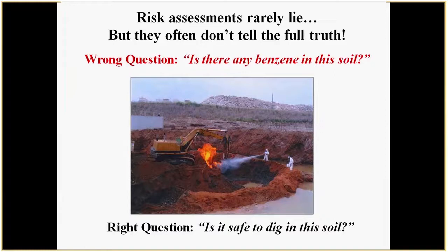So the right question is, to start with, is it safe to dig in the soil? In this case, there wasn't any benzene, or very minimal levels, in the soil, but there were really high levels of TPH. Gasoline vapors in the soil caught on fire every time they dragged a backhoe bucket through it. It's a big deal. It's definitely a potential concern for petroleum contaminated sites, though very rare to happen. So it's more than just direct exposure and more than just benzene.